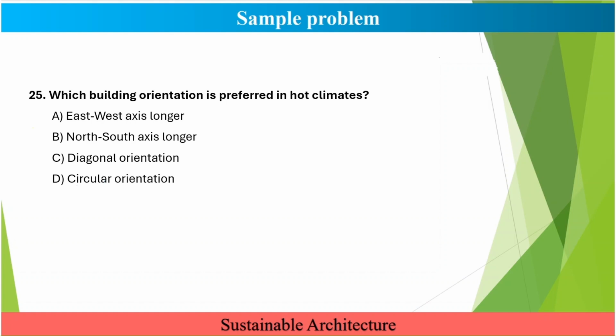So we will be facing our building towards east west, or facing towards the north south face. I am not talking about the axis. To reduce the south or north face of the building, which is where the maximum radiation is. So if your building will be facing towards the south, the solar radiation gain will be maximum. So you want to maximize solar radiation gain or minimize it in this particular context? Minimize.